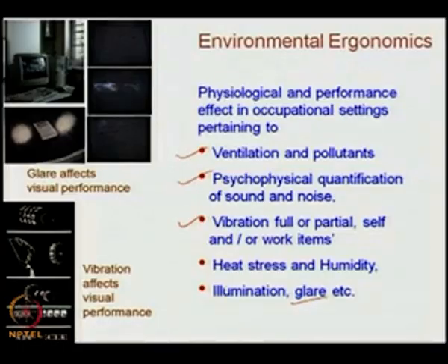Like in this case, the lamp source on this table is on the top, but the two shadows are coming here and it gives this comfort glare. But in this case, the computer screen, the light source is coming from here and it reflects to the eye, and all the image of the outside window comes through this screen. So, whatever I would like to concentrate on here, it is difficult. So, this is disability glare, and in this one comfort glare.